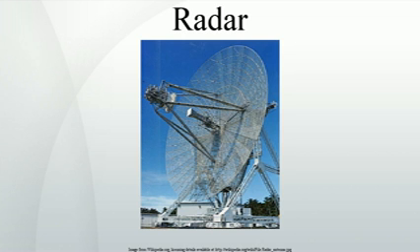Reduction of interference effects. Signal processing is employed in radar systems to reduce the radar interference effects. Signal processing techniques include moving target indication, pulse Doppler signal processing, moving target detection processes, correlation with secondary surveillance radar targets, space-time adaptive processing, and track before detect. Constant false alarm rate and digital terrain model processing are also used in clutter environments.